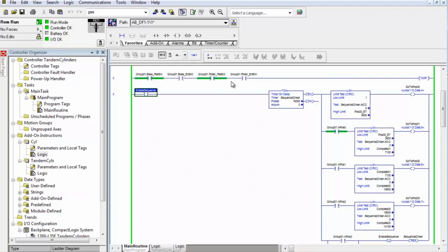So if you're going to do this in an actual sequence that matches the real world, you've got to sit down and really think this through and maybe draw up a chart and have it say switch 0 off, switch 1 on, etc., position such and such. I have included in the manual some graphics to help you out somewhat. And again, this is about creating and troubleshooting add-on instructions, not using them.